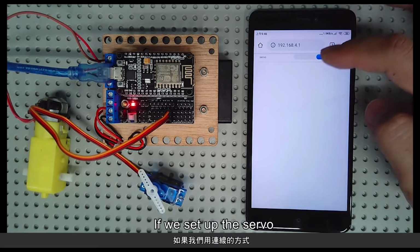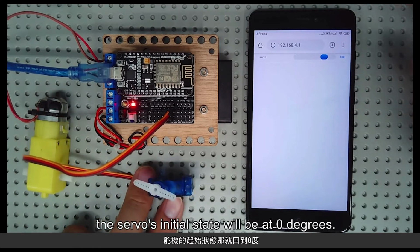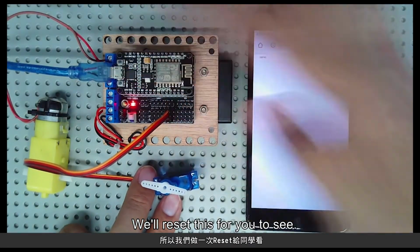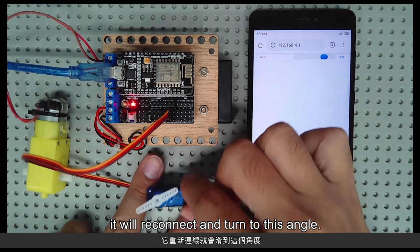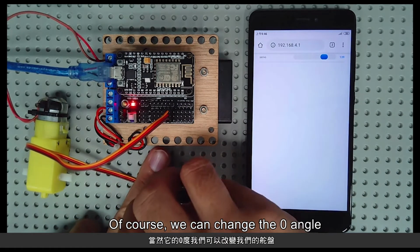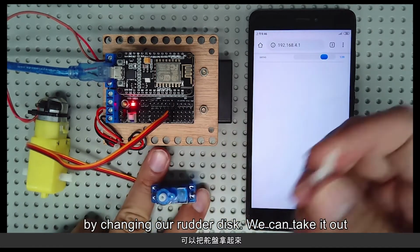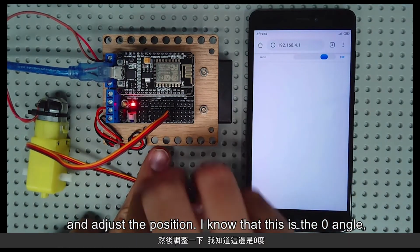If we set up the servo through this connection, the servo's initial state will be at 0 degrees. We'll reset this for you to see. After I press the reset button, it will reconnect and turn to this angle. This position is its 0 angle. Of course, we can change the 0 angle by changing our rudder disc. We can take it out and adjust the position. I know that this is the 0 angle.